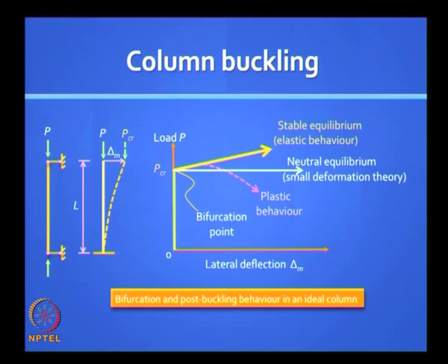So these things are well known. That is called large deformation analysis, which you do not normally study at an early level, but in elastic stability you get a solution like that. Okay, now if the two ends are simply supported or pinned like this, the buckle shape will look nicely symmetric, and this is a standard case which Euler explored, and this is called the Euler buckling load for the standard case where the solution is pi squared EI by L squared.